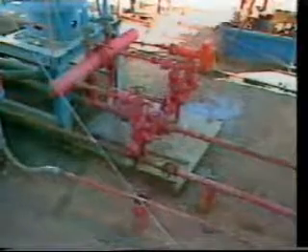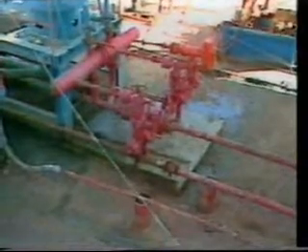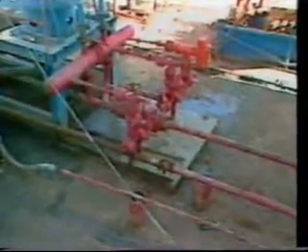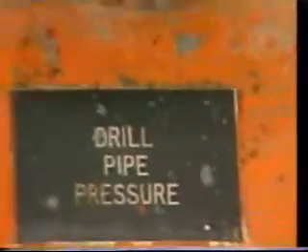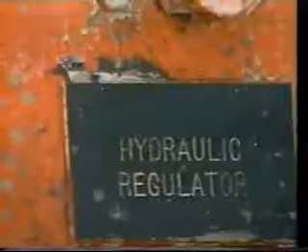The circulating mud is detoured from the closed-off annulus below the BOPs to a choke manifold, where it is passed through a choke or adjustable valve controlled from a remote panel. By carefully adjusting the size of the choke opening, the drilling engineer can maintain the pressure in the annulus required to prevent further kicks until the well is balanced once again.